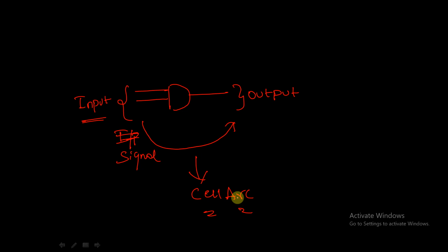For a cell there may be more than one timing arc, and by the information of the different timing arcs that exist for a cell we can calculate the delay for each path. That helps in timing analysis and optimization. This is basically a combinational circuit, a logic gate.